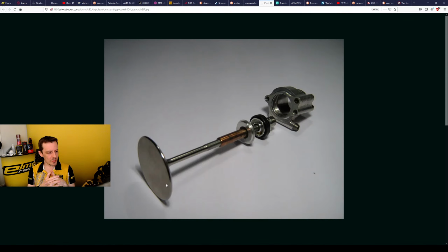So where were we? So material stuff and temperature things. Okay, yeah. So exhaust valves don't have that luxury. So you need to be able to either run a much wider valve seat to transfer more heat from the dish into the cylinder head, but that's not ideal on racing engines because you need to maximize your flow area on the exhaust port in relation to the cylinder, or then you can just run a smaller bore instead. So you don't really want to run a wide valve seat.